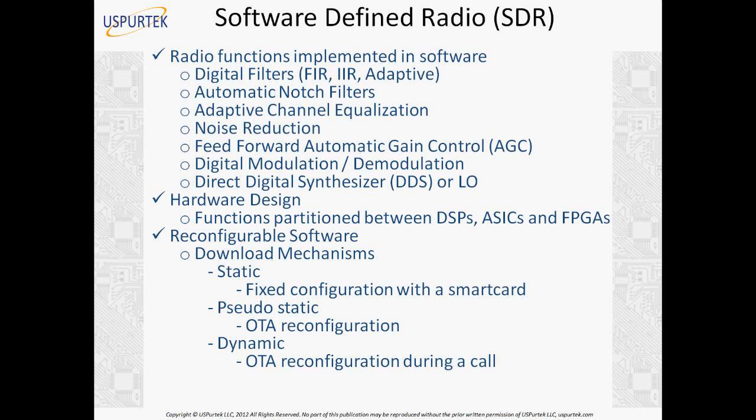We constantly use some hardware implementation to monitor the output frequency, and if there is any variation, we compare with the input. And if there is variation, we adjust the oscillator to maintain the frequency at a stable point, whatever frequency it's going to generate inside the receiver. So the PLL is used to stabilize the frequency of the oscillator. So phase lock loops provide you a very stable local oscillator. Remember, previously we said that in any wireless receiver, stability is very important. So PLLs help us achieve that stability in the frequency that is generated inside. The same holds for transmitters also.